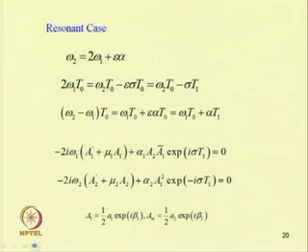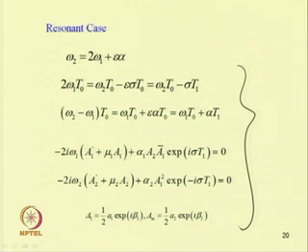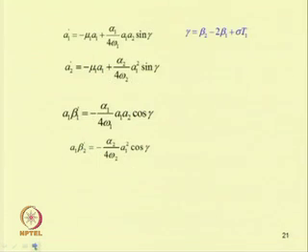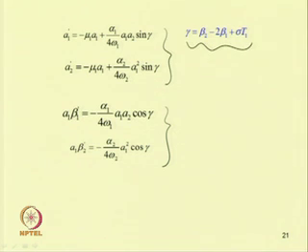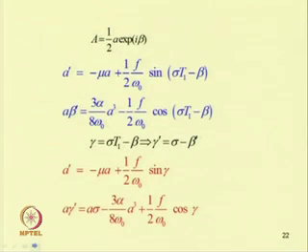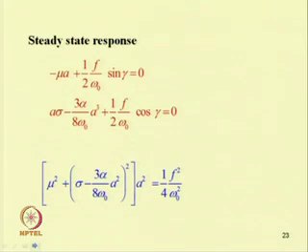And in case of resonant condition, if we are considering this internal resonance type, we can take omega 2 equal to 2 omega 1. Depending on the internal resonance condition, one has to take it in this form, and as already discussed, it will reduce to a set of reduced equations. These are the reduced equations, and to write them in autonomous form we can use this gamma. It will reduce to a set of equations, and for steady state it reduces to this equation.